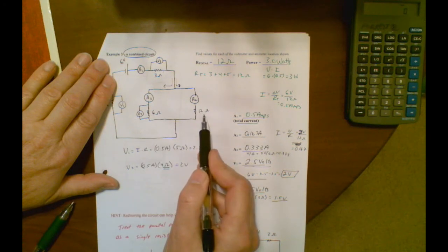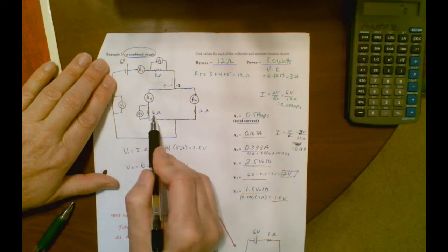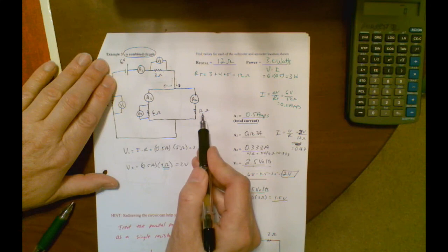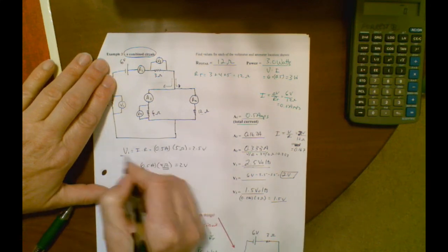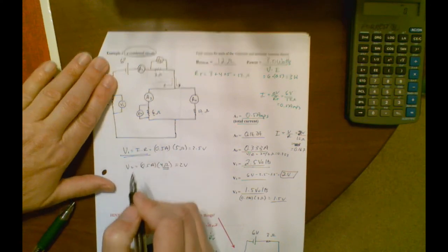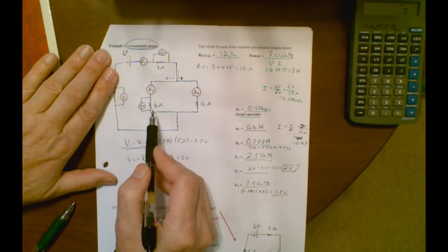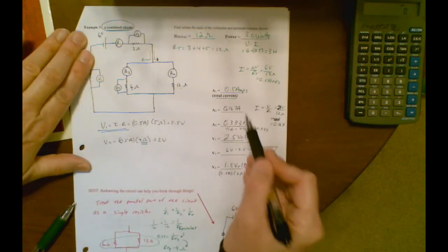There's twice the resistance in the right branch as the left branch, and so therefore twice the current will go in the left branch compared to the right branch. Why? Because the voltage would have to be the same. We know that voltage overall is equal to I times R. So I could think proportionally 2/3 of the half an amp would go here, 1/3 of the half an amp would go here. That agrees with what I got.